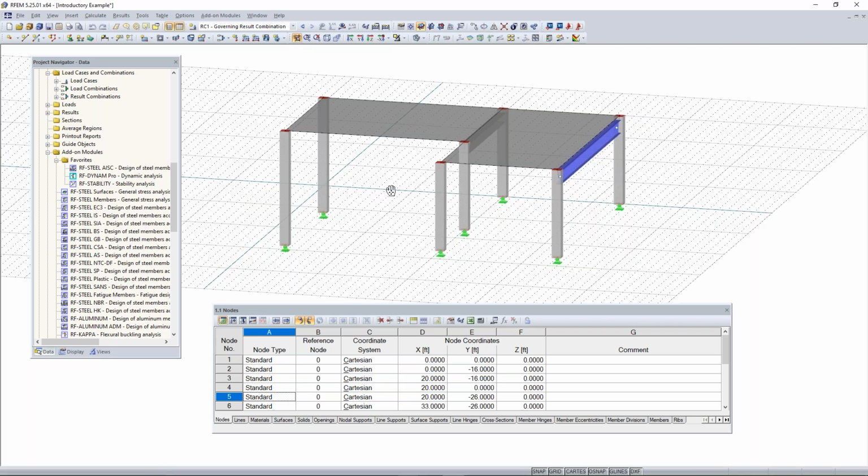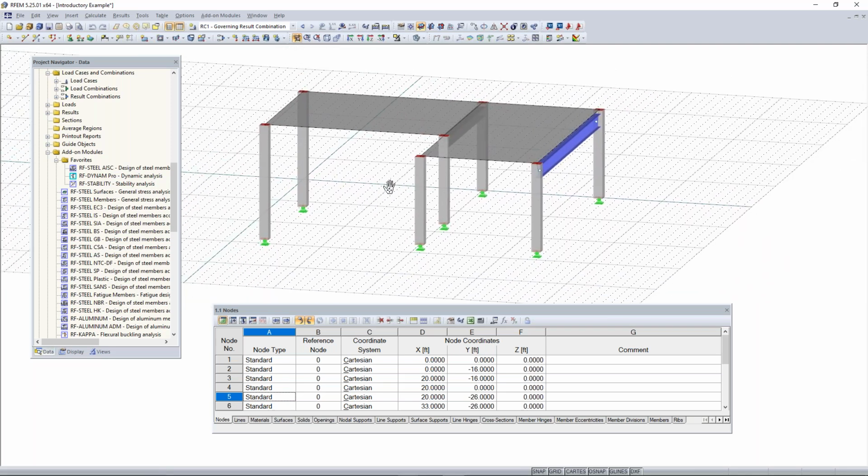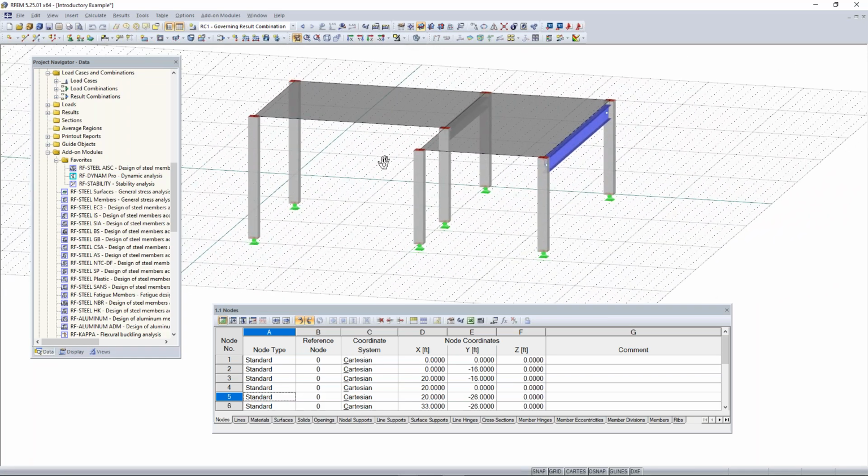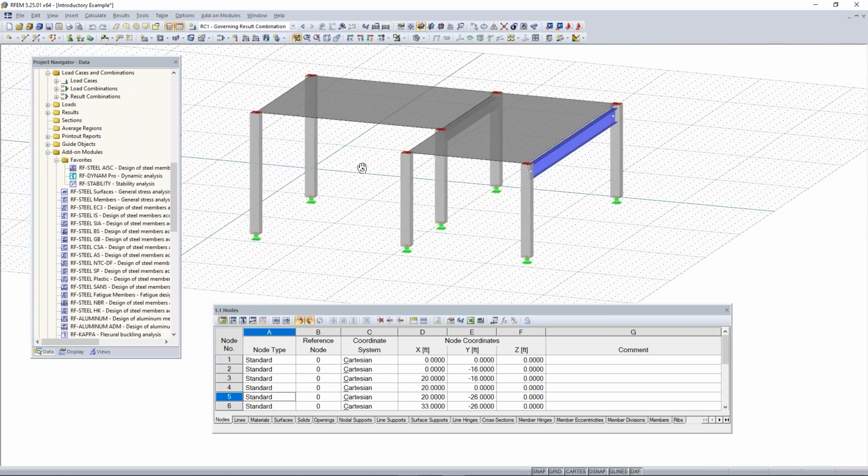You can click on that and then you can left click to move. You can also hold Shift, and then you can zoom in and out with left click, and then you can hold Control and rotate the model. So that's pretty handy. You can also do all of this with the arrow keys on your keyboard, and they perform the same function.